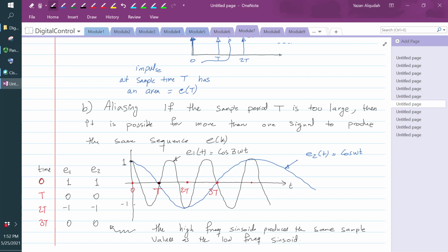And since we have two signals with different speeds, one of them being 3 times the frequency of the other, if I do not choose the sampling frequency or the sampling period correctly, I can end up with this effect that is called aliasing. Okay, we're going to look back at this aliasing later on when we look at the star transform. I'm going to stop at this topic, and in the next module we'll look at the digital to analog conversion.